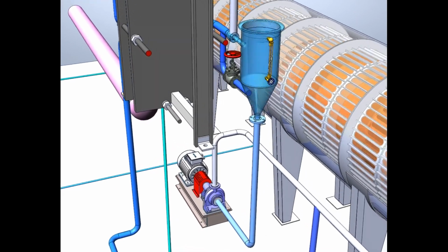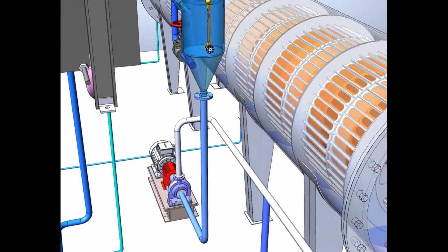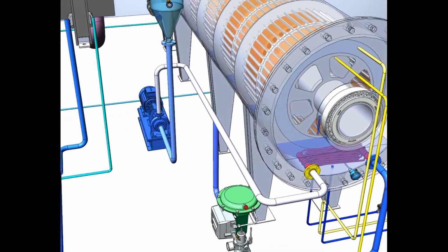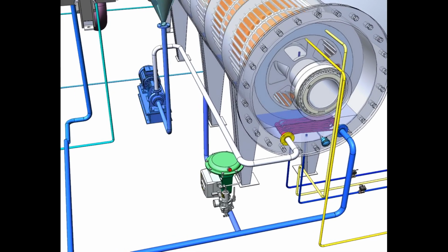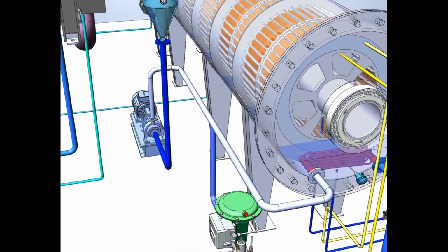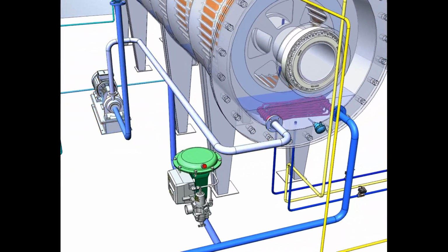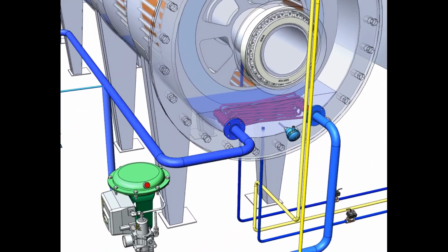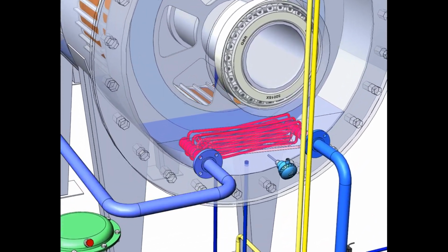For the circulation of the coolant in the circuit, a cantilever centrifugal pump is used, into which water is supplied from an open tank. The pump delivers a coolant with a temperature of 27 degrees Celsius to the tubes of the heat exchanger located in the lower part of the mass transfer apparatus under the water level. Due to the low water pressure in the apparatus, it boils intensively, forming steam, which then passes through the layers of nozzles. The water in the tubes is then cooled from 27 to 23 degrees.